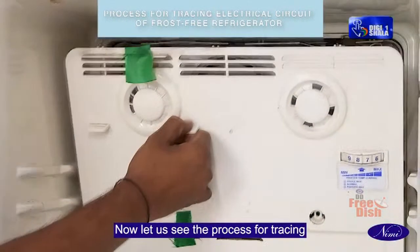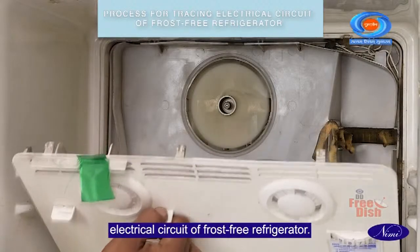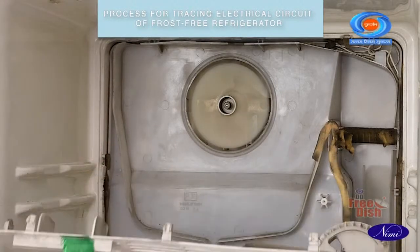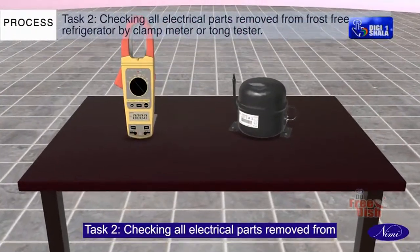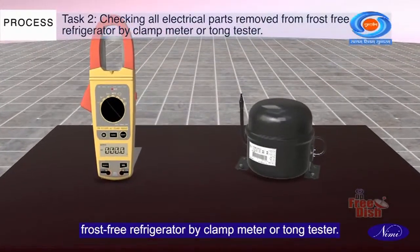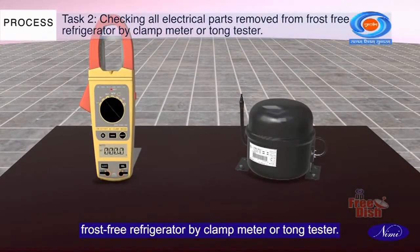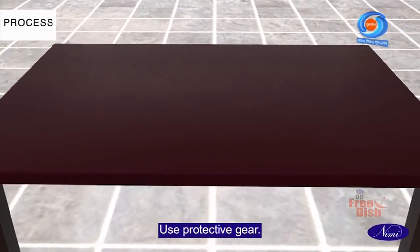Now, let us see the process for tracing electrical circuit of frost-free refrigerator. Task 2. Checking all electrical parts removed from frost-free refrigerator by clamp meter or tong tester. Use protective gear.